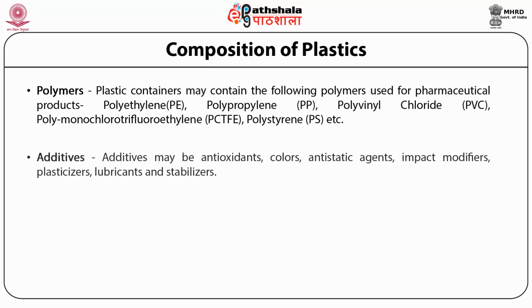The second one is additives. Various types of additives can be used during the formulation or manufacturing of plastics. They may be antioxidants, coloring agents, anti-static agents, impact modifiers, plasticizers, lubricants and stabilizers.